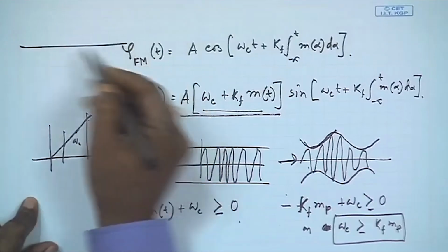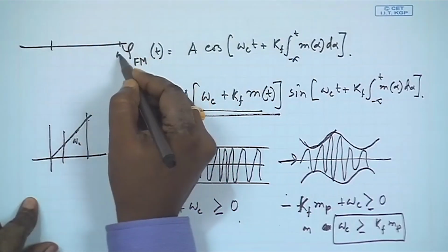Okay. So, basically my carrier frequency must be bigger than the frequency deviation. This is something I will always be doing, because I know from Carson's formula that the bandwidth is more than 2 times this deviation. If my carrier is not even bigger than this, there will be aliasing, right. We are actually putting it at the carrier omega c.